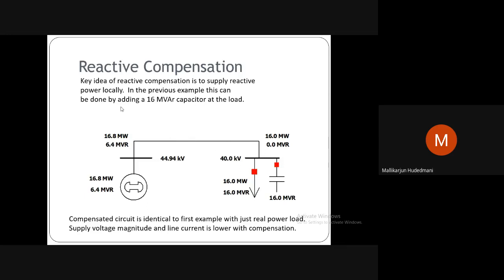So this is one reactive power compensation technique by the shunt capacitor concept, which is simulated in PowerWorld. I have taken the example directly because it's very easy to understand. On removal of this capacitor, definitely the reactive power needs to be supplied by the generator. On insertion of this capacitor, the MVAR compensates automatically. There is a sudden decrease of reactive power to 6.4 MVAR. This example by simulation lets us see how strong local compensation by a shunt capacitor is in operation.